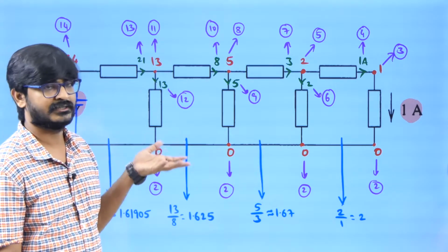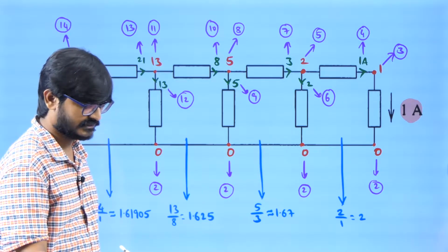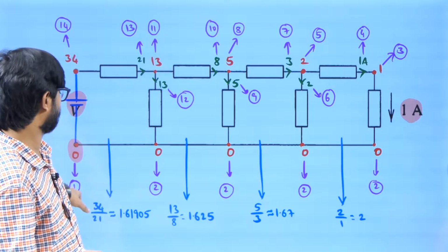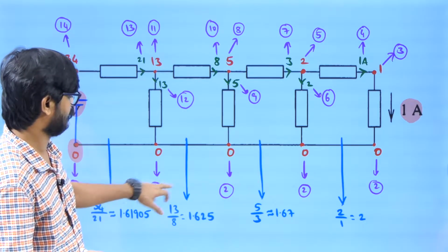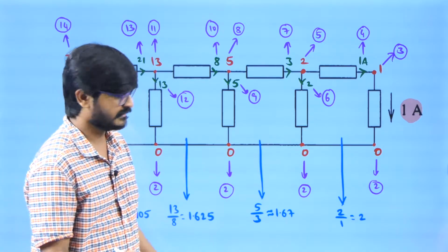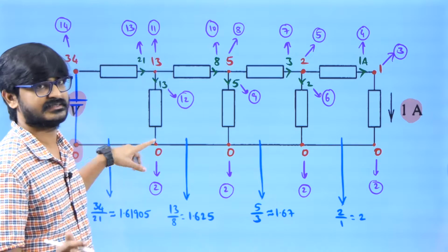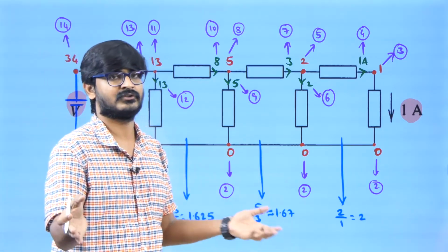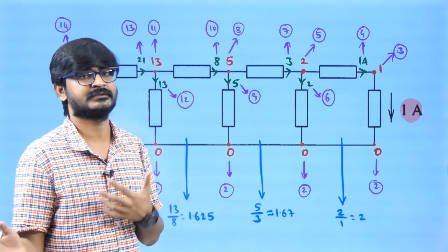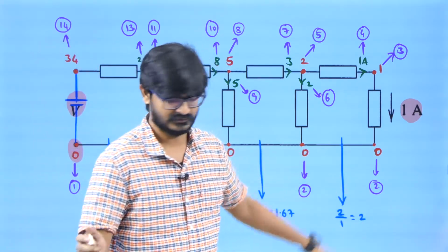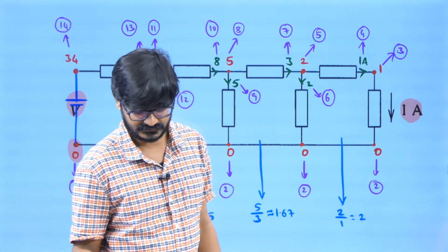So only potential difference matters for us. So I will be taking this potential as 0. Now those who are reading the PDF, they can see the step numbers I have placed here. 1, 2, 2. So if this potential is 0, then every potential is going to be 0. The reason is resistanceless wire. Just now we have seen if some finite current flows in a resistanceless wire, then the potential difference has to be 0. So if this is 0, 0, 0, 0, 0. So I have done all this.